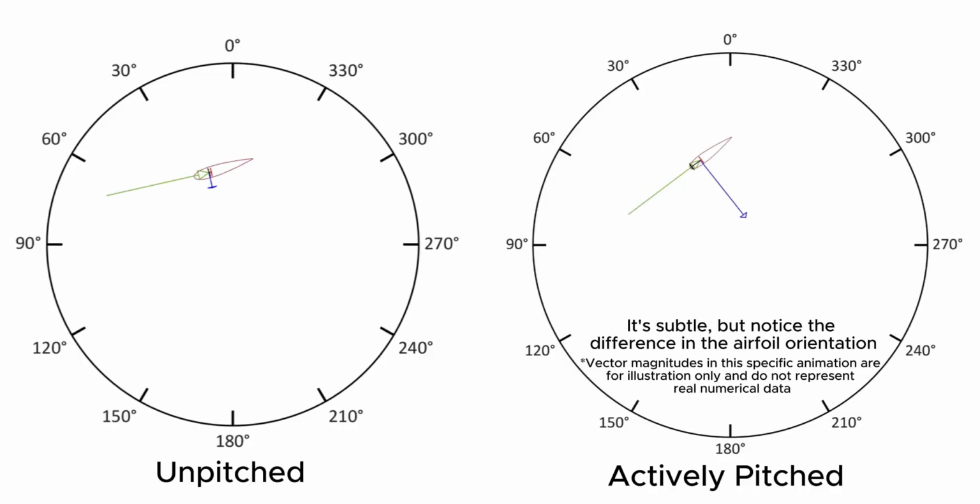So there you have it, the effects of dynamic stalls on Darrieus turbines. It's definitely a net positive. If we can find a way to abuse dynamic stalls on Darrieus turbines, active pitching, in theory we should be able to massively boost and amplify the amount of torque generated per blade, and therefore push the Darrieus turbine to even higher tip speed ratios and therefore generate more power.